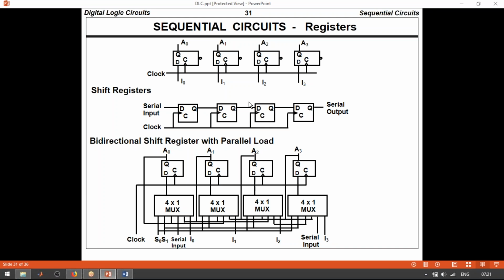For the third clock pulse the 0 will come to this side, and on the fourth clock pulse that 0 will come to this side. That means after the 4 clock pulses the 0 will be shifted here. So each element will consist of 0, 0, 0 and here it is 1, because my input is 1 0 0 0. Only after the 4 clock pulses are we getting the exact output. Before that the output of this flip flop will be unknown or in a reset state.